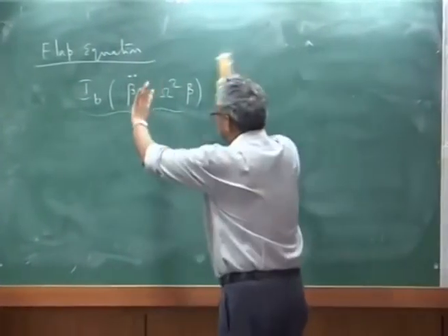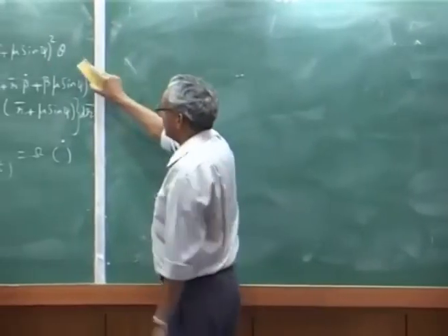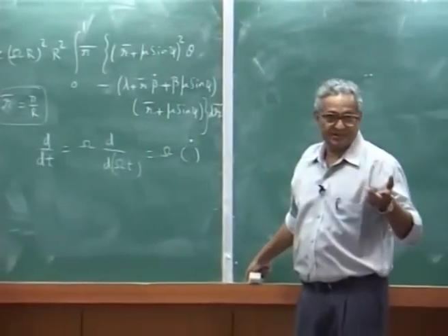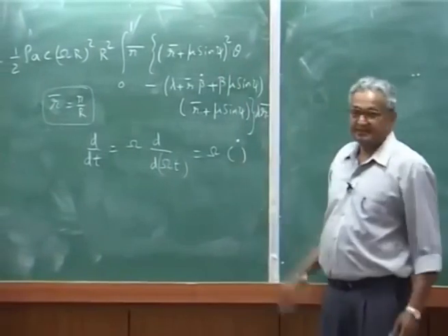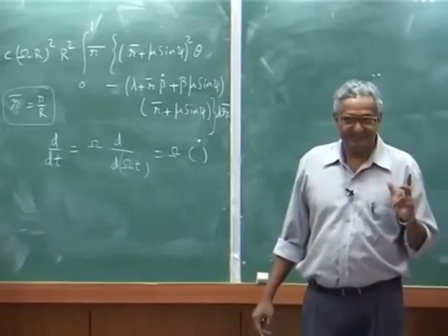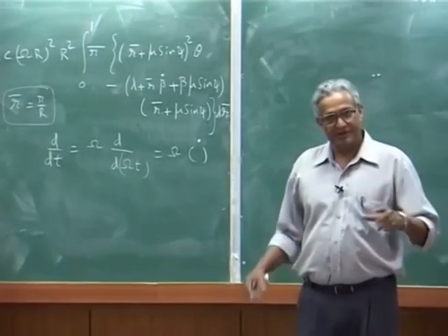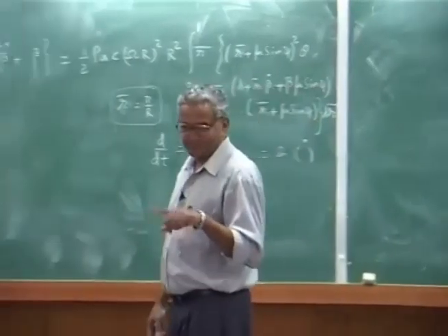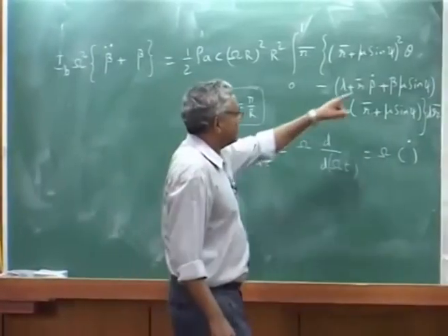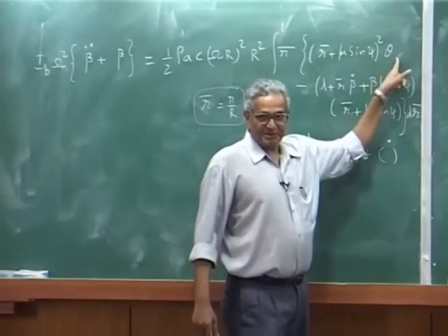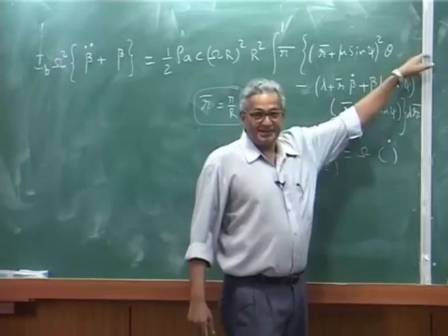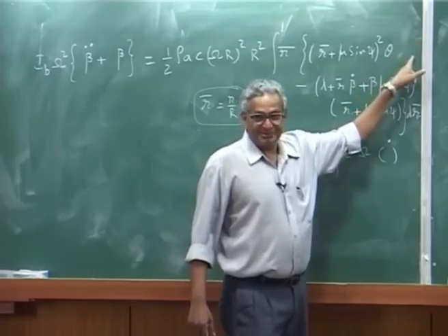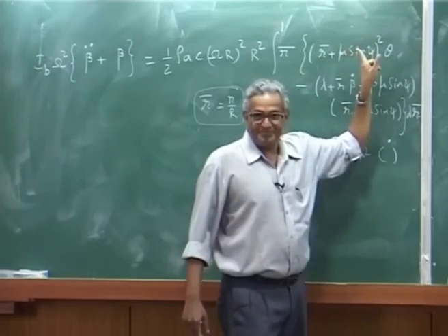And even theta is, please note, this is the theta the pilot gives. That is theta I. If you have a twist built in, then twist will come here. That will have a theta twist r bar. That term also will come here.